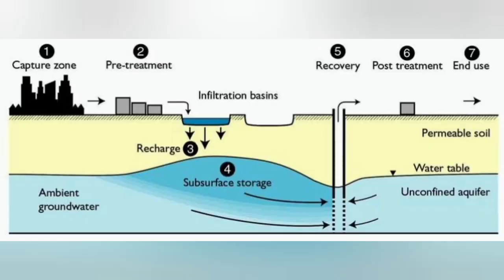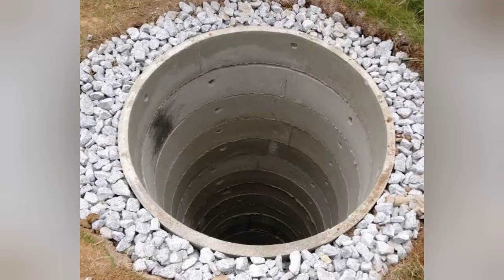The maps are: maps showing the hydrogeological units demarcated on the basis of their water bearing capabilities, both at shallow and deeper levels; maps showing groundwater contours to determine the form of the water table and the hydrological connections of groundwater with rivers, canals, etc.; and maps showing the depth of water table, usually compiled for the periods of maximum, minimum and mean annual position of the water table.